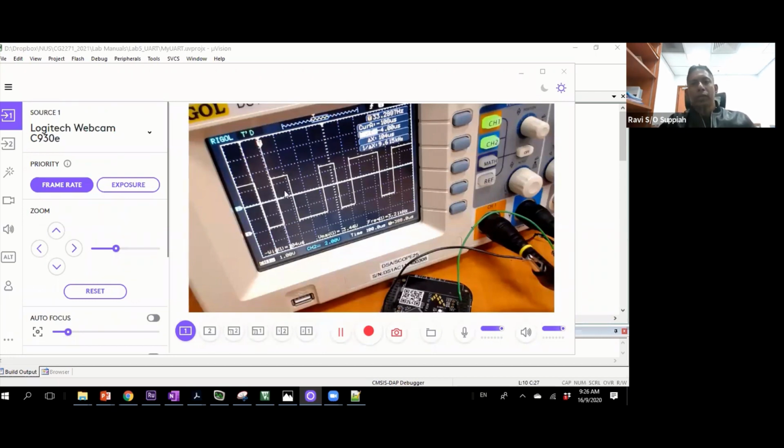So after the start bit, you have a few bits of information. So you have 1, 0, 0, 1, 0, 1, 1, 0. Correct. So this relates to what? So 1, 0, 0, 1 is 1001 is 9, correct? And then 0110 is 6. All right, so you can see that you transmit out the least significant bit first.